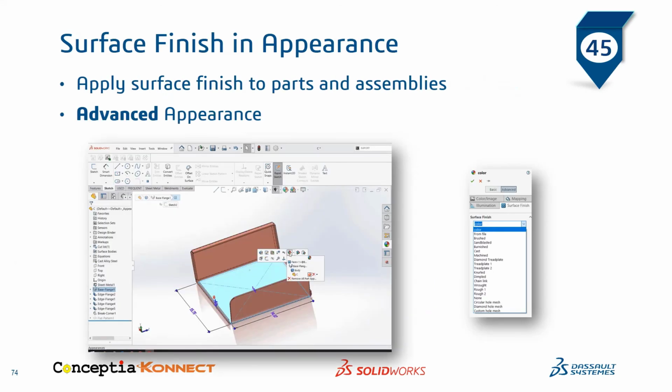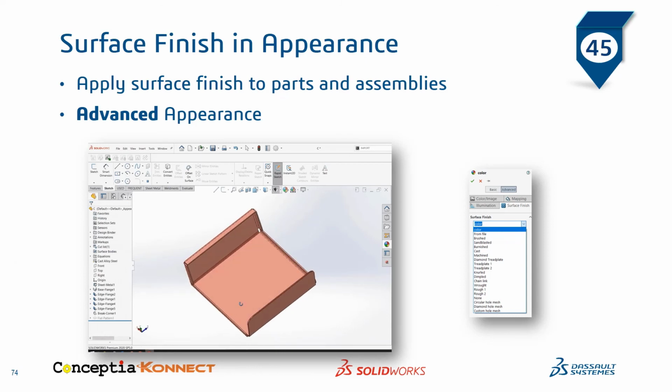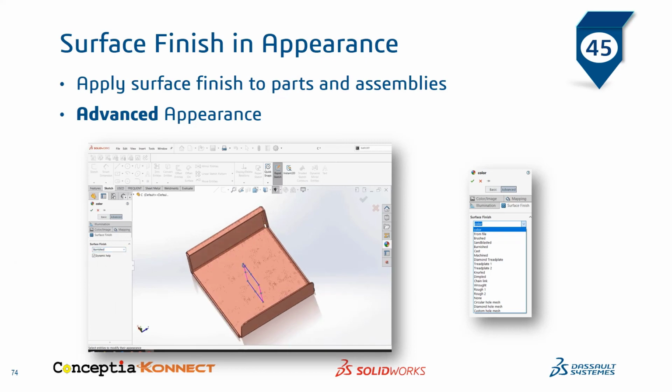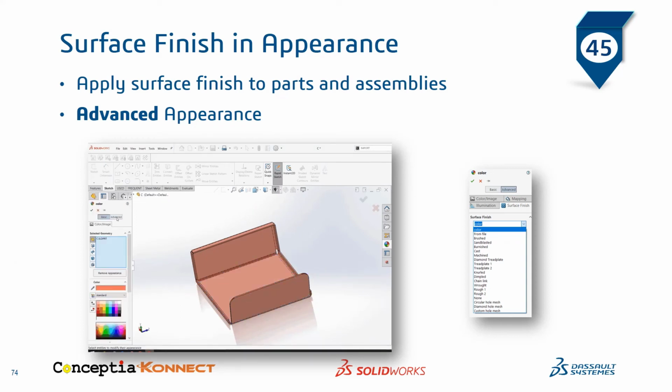Number 45, surface finish in appearance. How many of you have applied the surface finish after giving the color scheme to the model? Go to advanced mode rather than your basic mode and choose your surface finish type. So you will have multiple options such as brushed, cast, machined, knurled. Choose any one of it and select OK.